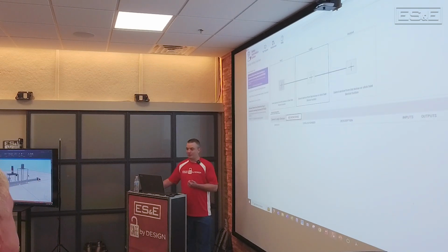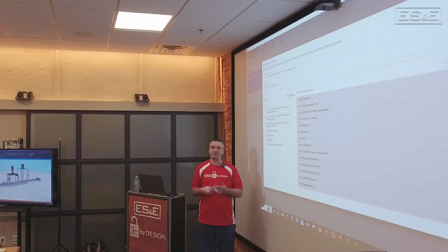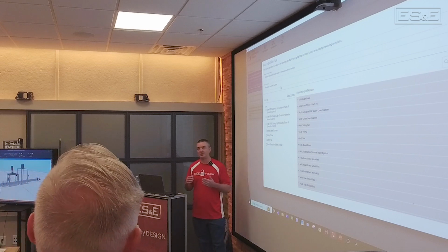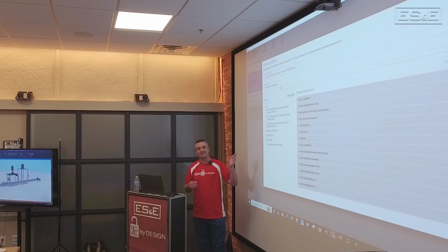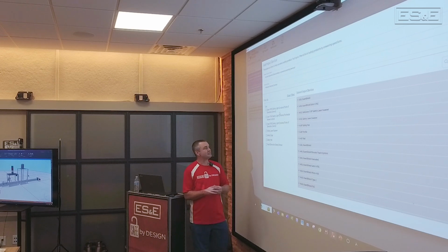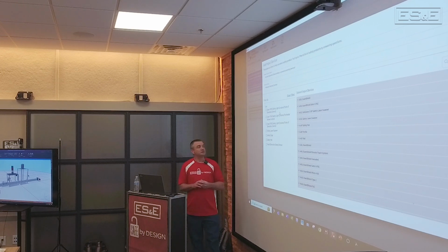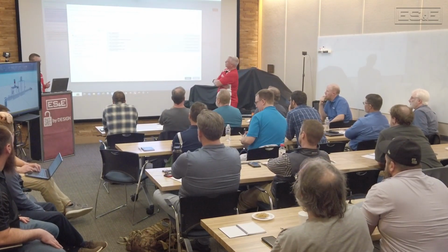So again, we will need to specify the actual particular devices, and the reason for that is, as I mentioned, SISTEMA takes into account the mean time to dangerous failure. So some of these components, depending on what you're using exactly, have different mean times to dangerous failure. So that starts designating this information for you. You'll notice here, because we've said presence sensing devices, it has automatically filtered down what all the presence sensing devices are. So you see point of operational control and then perimeter access control.